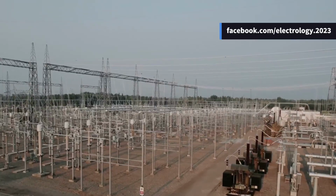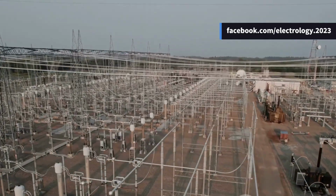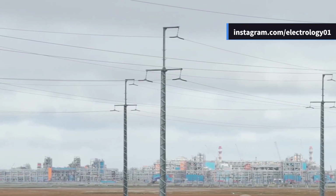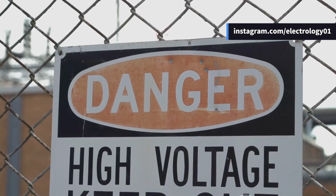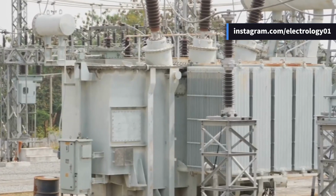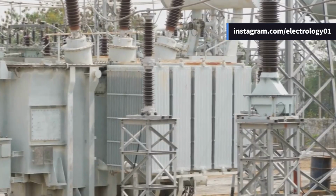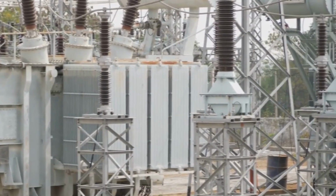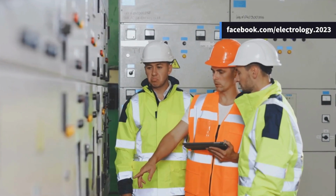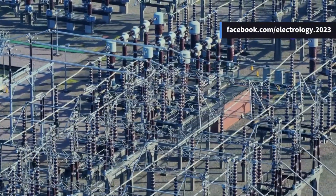To find the economical transmission voltage, we assume that we already know the power that needs to be transmitted, the generation voltage, and the length of the transmission line. Then we pick a standard transmission voltage and estimate the various costs involved. Now here's what happens. The cost of transformers at both the generating and receiving ends increases as we raise the transmission voltage. Switchgear also becomes more expensive with higher voltage levels. Lightning arresters are another cost that goes up significantly with the increase in voltage.